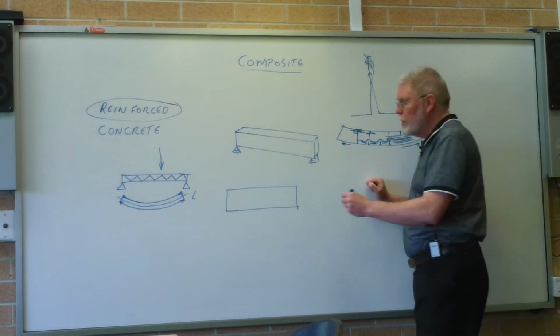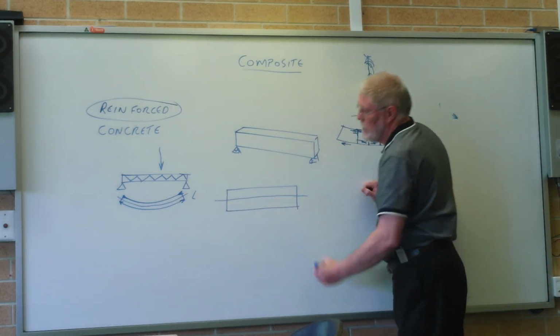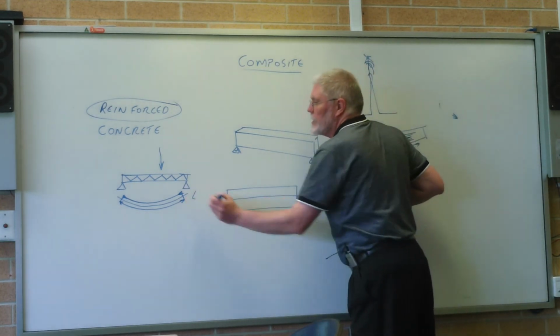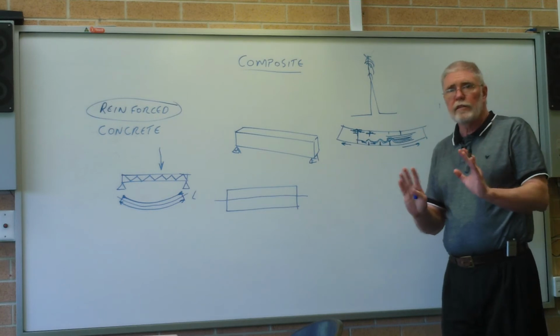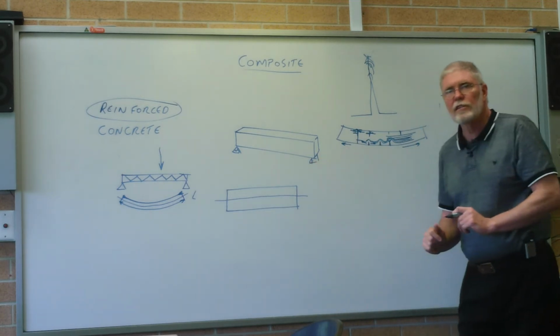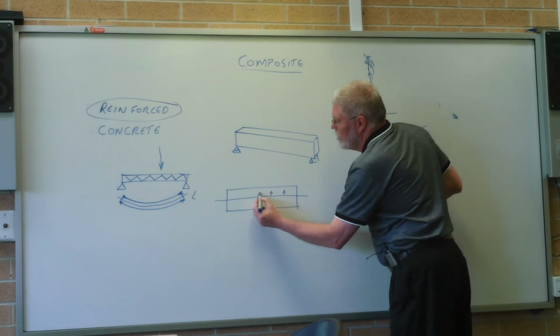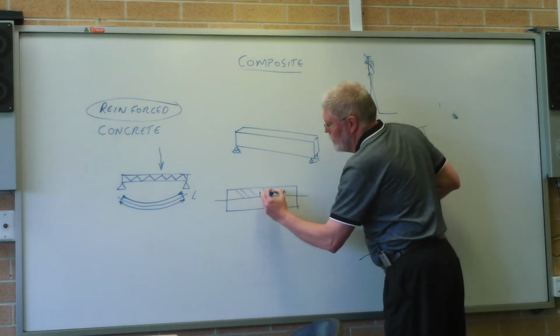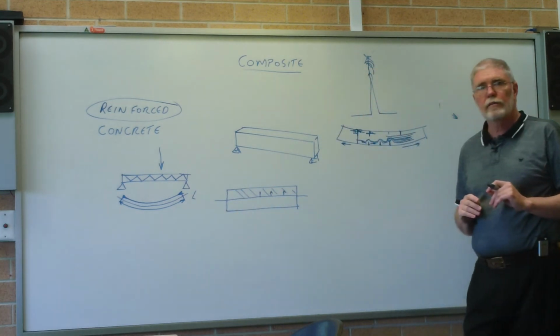I know that the weakest point, if I say here's the middle axis, the neutral axis, is the one that doesn't change in length. All right, that doesn't change, so it's going to be fine just as it is. Everything above that, this range up here, is going to be shorter when it's deflecting.